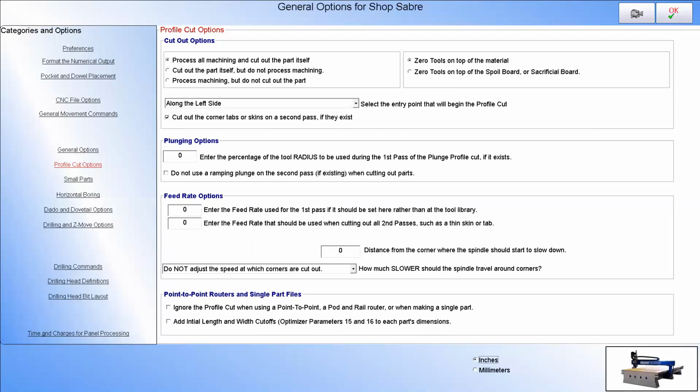Well, if you check this box right here, then what'll happen is that if you have a 20 by 30 piece, the material of that part is 20 inches by 30 inches. It'll add a 1/4 of an inch to it, and it'll first cut off that 1/4 of an inch so that the whole part is squared off, and then it will machine that part according to whatever is appropriate.